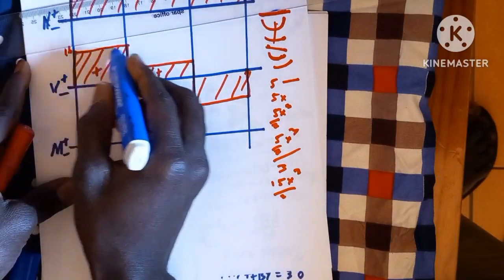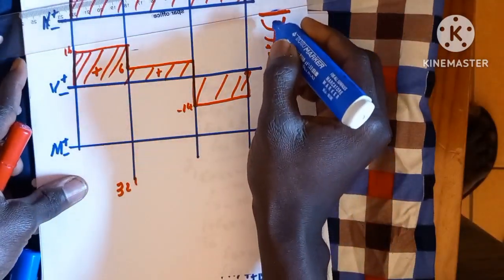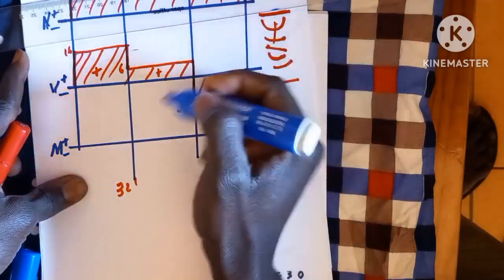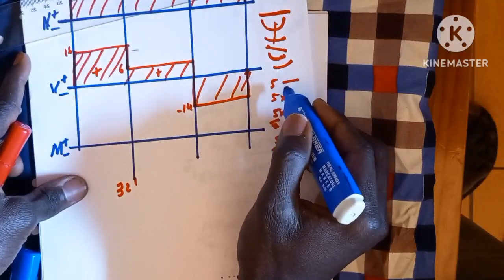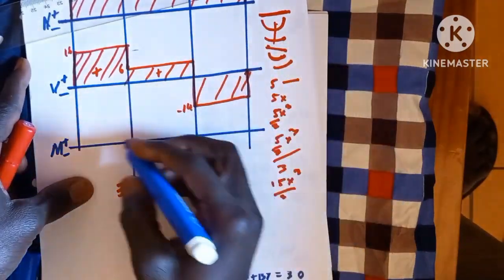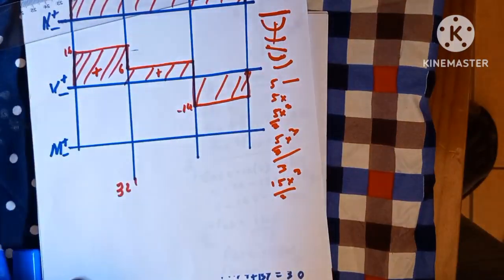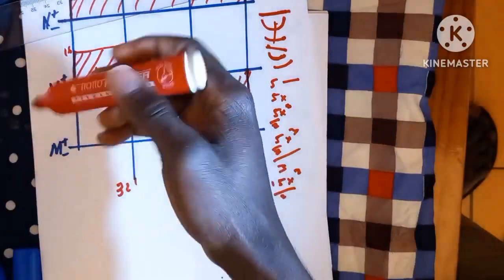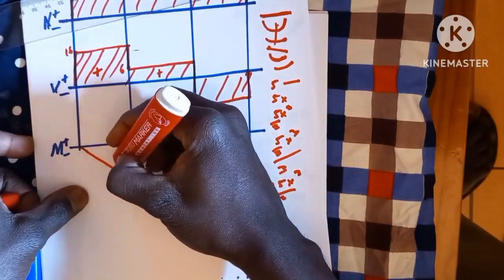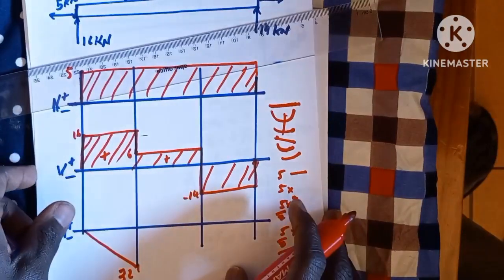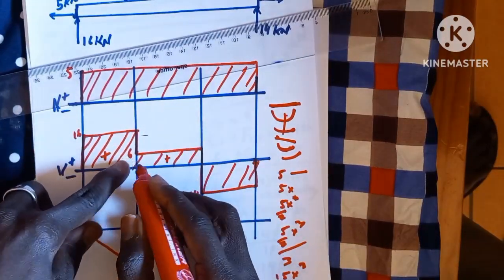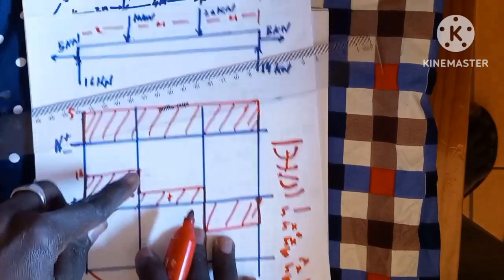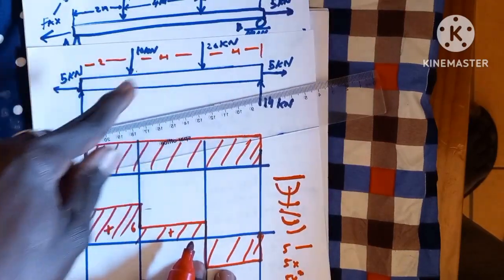Since this is a straight line here, and we already know the relationship for the shear force graph, when it is a straight line, the next one under it is going to be an inclined line. So this is going to create an inclined line here in the negative direction, right? So the next graph is this section, right? And the height of that is 6. So 6 will be multiplied by 4, since 4 is the base of that.